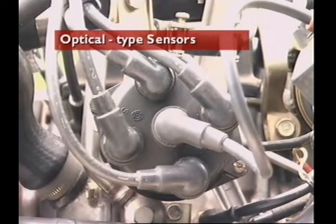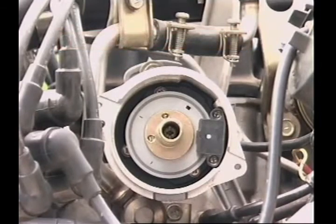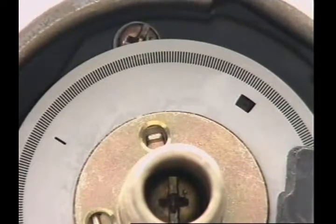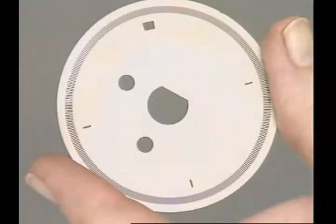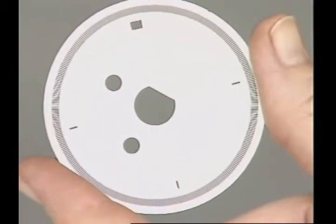Crank angle position and engine RPM can be detected optically. A signal rotor plate is attached to the distributor shaft. It has 360 slits at 1 degree intervals on its outer edge. Inboard of the 1 degree slits are 4 slits, one for each cylinder. They provide the reference points for the ignition timing and the fuel injection. One is larger than the others to provide the signature effect for the number 1 cylinder.